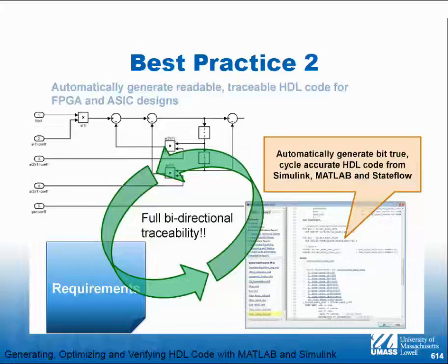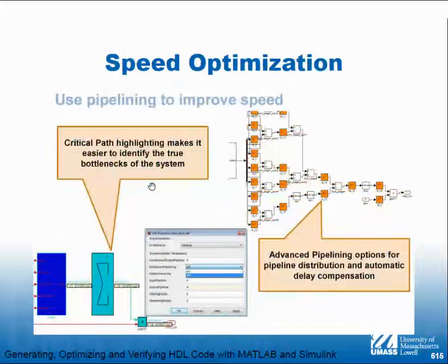All right, I did this stuff. I want to do a peer review, right? That's what we do. So you create a system design, you generate code with HDL Coder, and then you do a static test of it. Right? So don't discount that. It's important, and don't let anyone tell you it's impossible. They even help you by putting comments in that reference back to the original design. It also has things that you can put in for optimization.